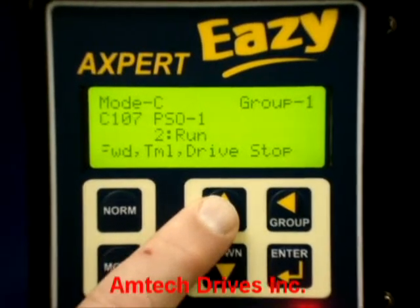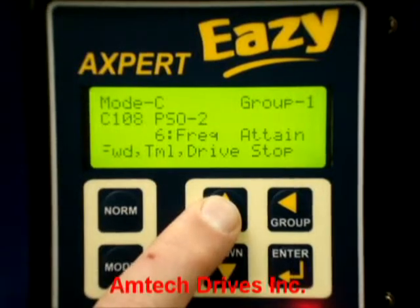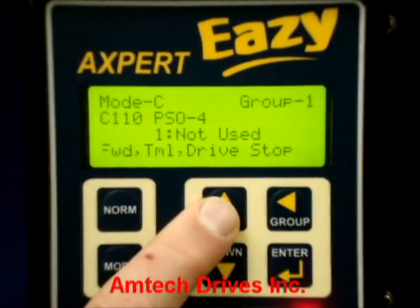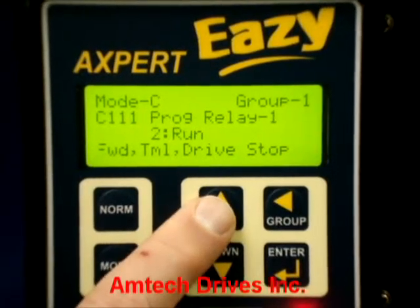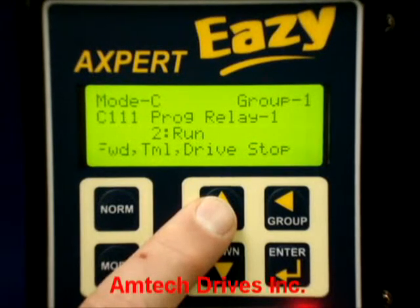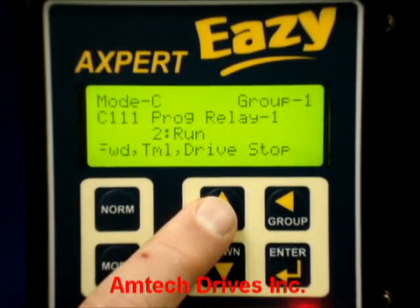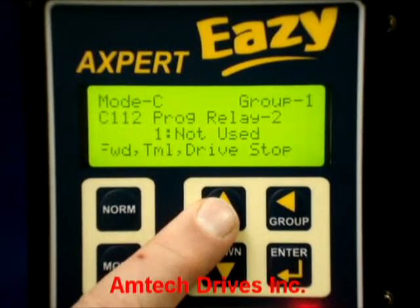If you look through the open collector outputs 1, 2, 3, and 4, you can change what you have assigned to your open collector outputs. And then C111 is your programmable relay 1. In this case, it's set to run, so whenever the drive's running, your contact is closed. And for relay number 2, it's unused at the time, but you can set that, and again, those are both Form C contacts.